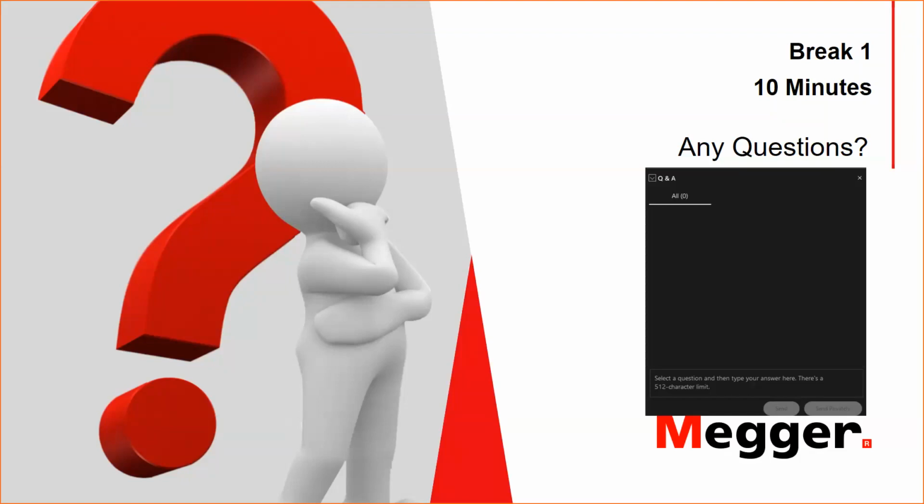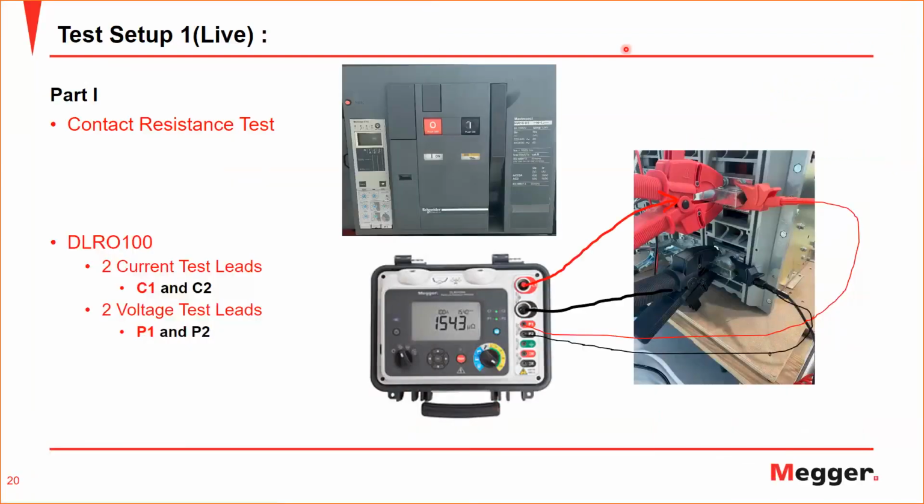So I have a picture on the previous slide, if I can just show you very quickly. I have the test leads showing here. I have one big test lead for the current, a red one and a black one, and 2 leads for the voltage. Now, when you're doing the connection to the circuit breaker, each phase, basically what you need to make sure is that the current leads are far away, and then the voltage leads are within them or inside the measured zone.